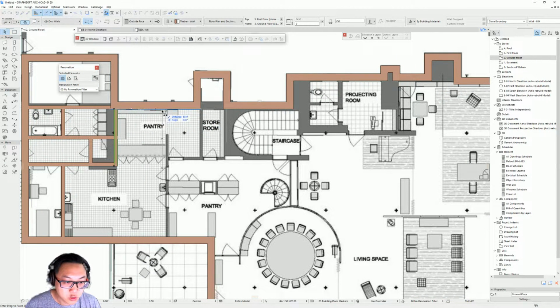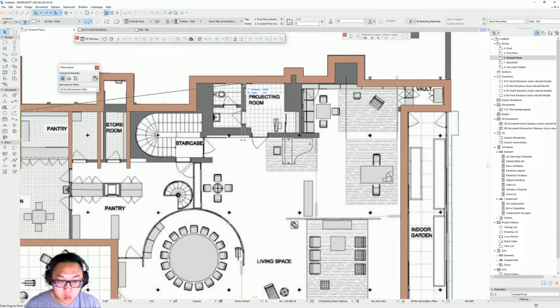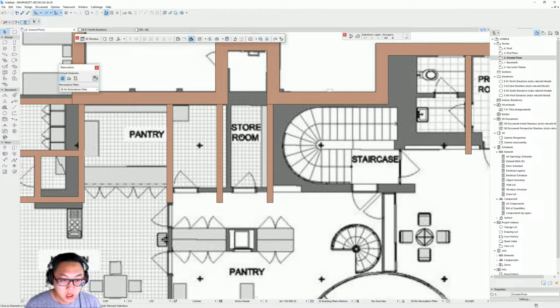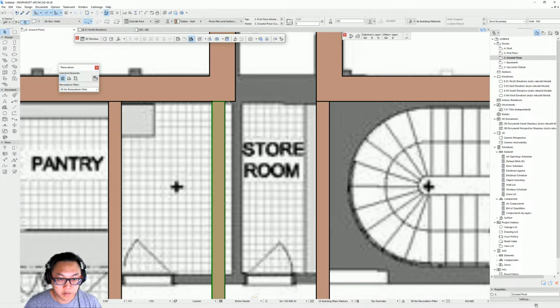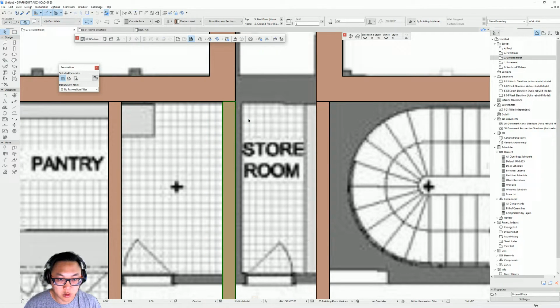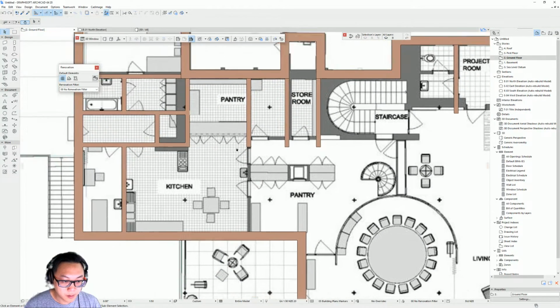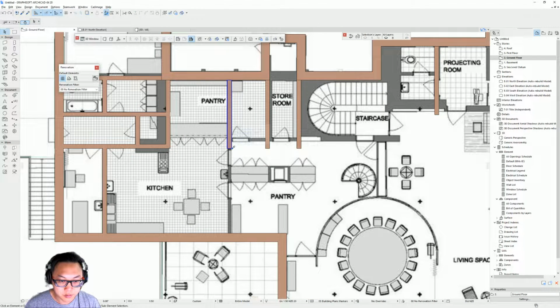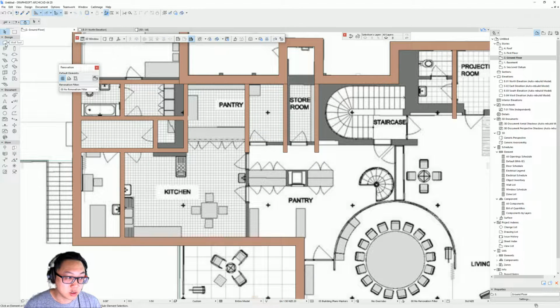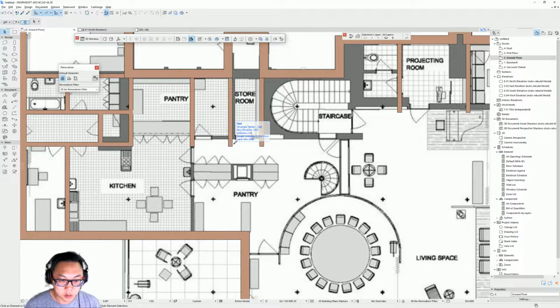So what I'm going to do is place one wall here, one wall here, one here, one wall here, one here, and that's it for now. Then I want to have that wall lined up to here, but as you can see, you can just select the wall corner and snap it to this other corner, so everything lines up, and that's okay. As you can see, I never go and click the wall tool here. I just suck the properties of the wall by using the syringe, by pressing Alt on the wall.